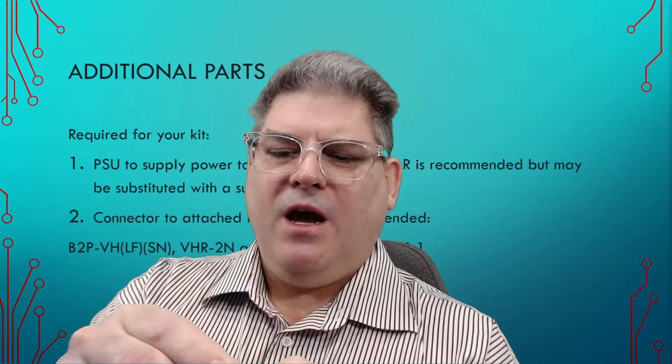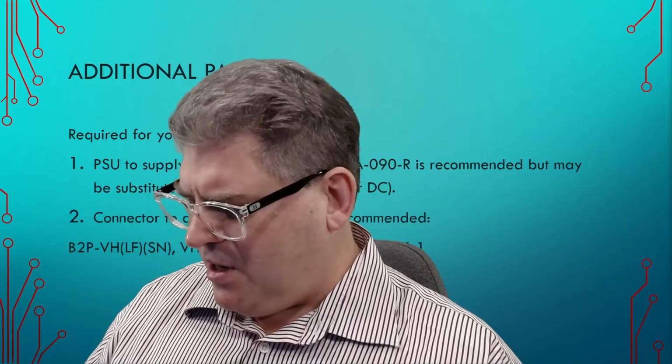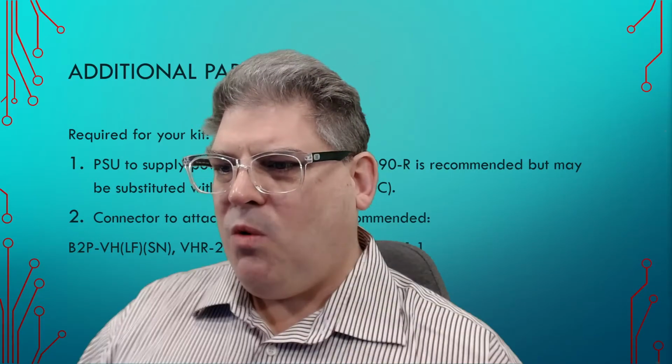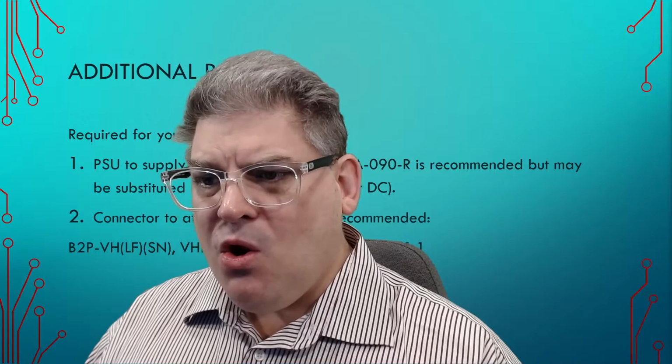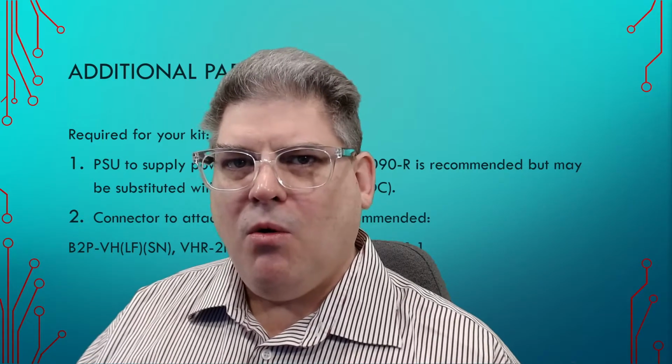Now the idea here is to give you some experience working with these sort of connectors because they're not as intuitive as you might think. One thing that you'll need for these connectors on the female side is the actual terminals. And so that's why it's important to get two pieces of the SVH21T-P1.1, which will go with the other components. I want you to get familiar with ordering complete sets of connectors and thinking about, well, I have the male, I have the female, and I have all the contacts.